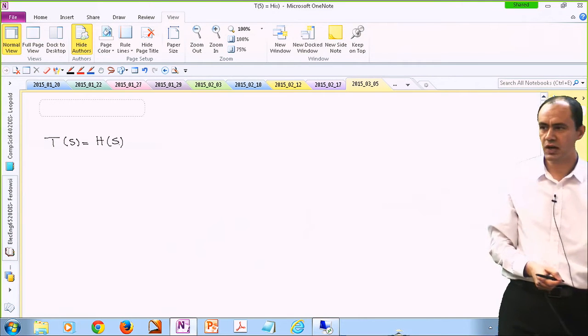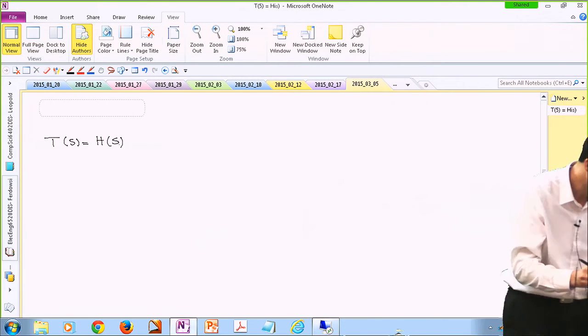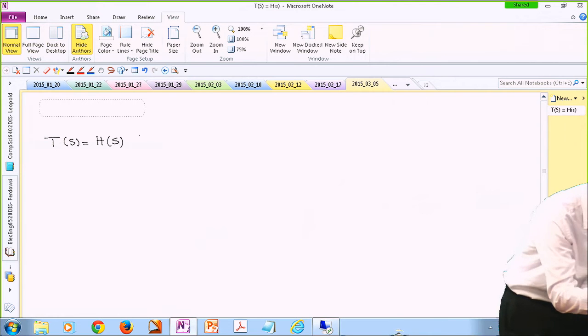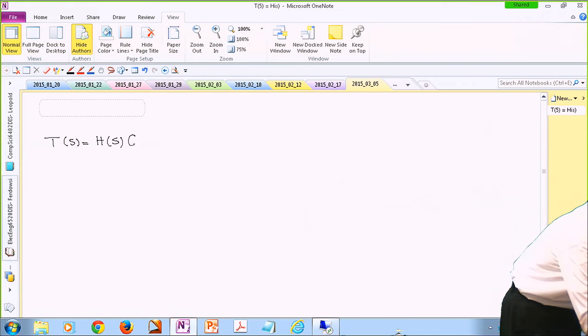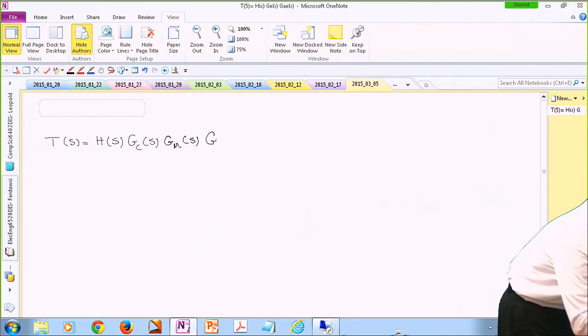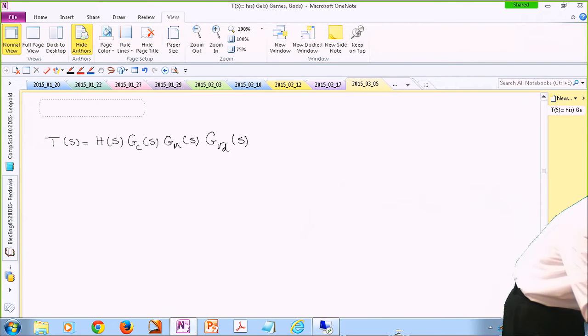We measure the output voltage, so there's a sensing network involved. Then there's a negative sign there in the loop gain. We never consider that negative sign. Then there is a compensation network involved that we don't know about yet. Then there is a modulating block. And then the converter itself has a control to output transfer function.